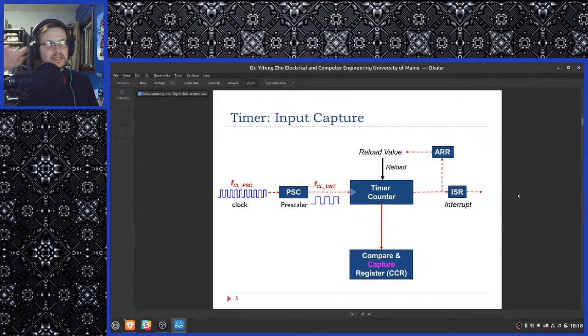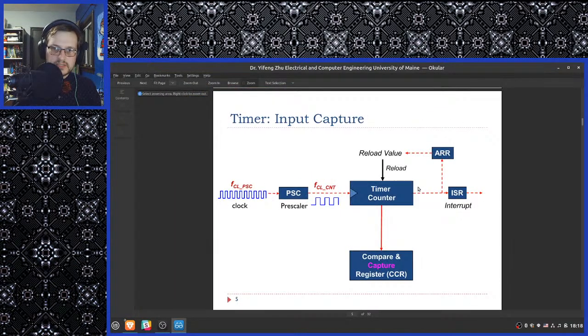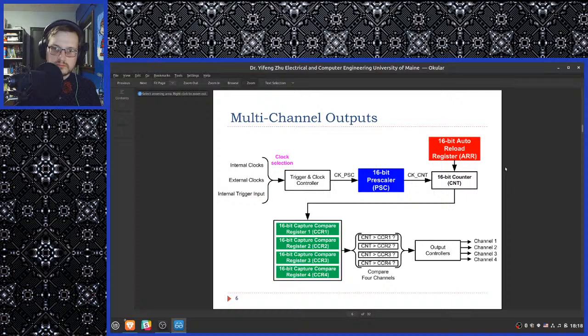It's a little tiny piece of memory that the peripheral itself holds. And it's basically just 16 flip-flops all lined up. So no, the timer does not interfere with the operation of the CPU. That's the entire point. But thank you. I'm glad you asked that, because that might relieve some confusion.